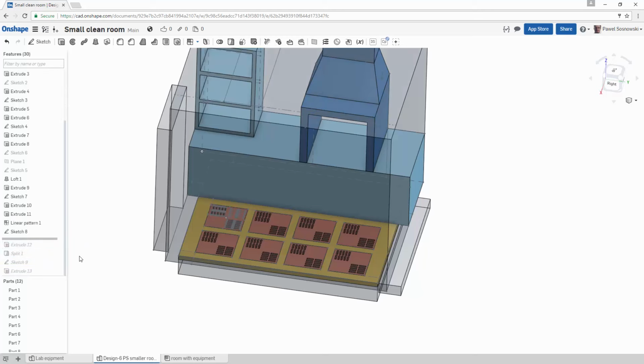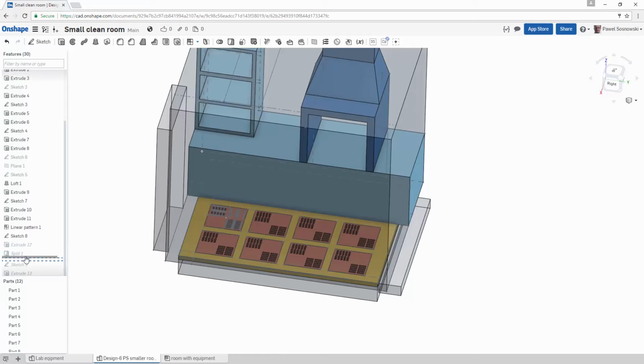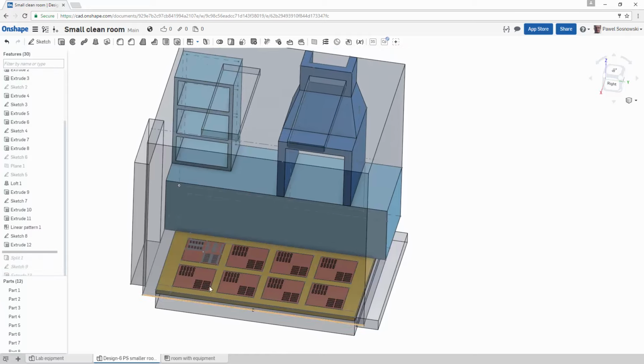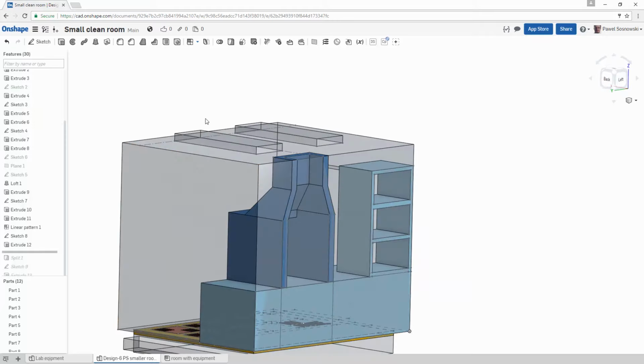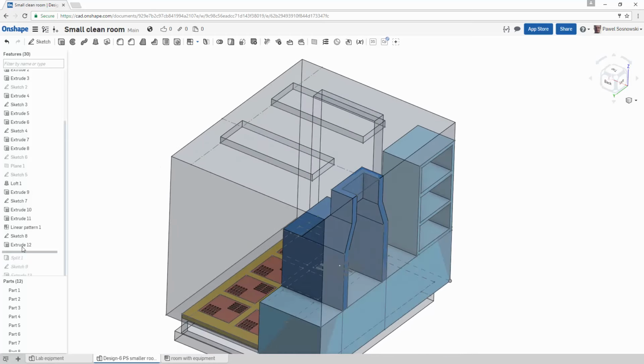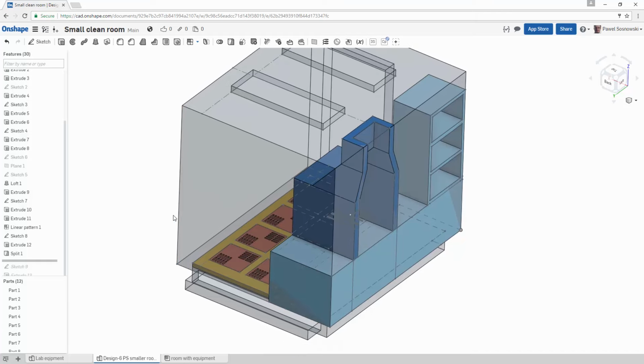Finally, we are finishing up several steps that we haven't done so far. So introducing top inlets that will be introducing only the fresh air. We are separating the outlet face, because before this step we had the whole top face selected as a single entity, and it needs to be directly split so that later the solver and the SimScale platform can recognize that this element over here is an outlet.